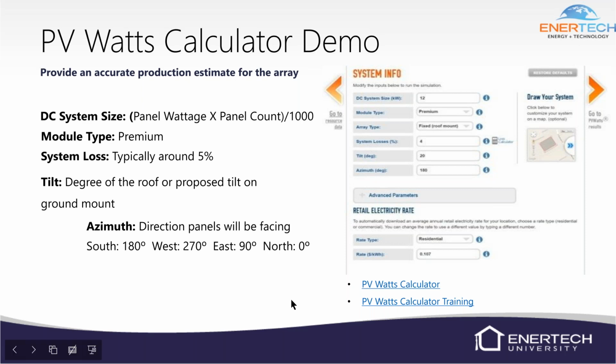So remember that the sun goes up higher in the sky in the summer and lower in the sky in the winter. So our tilt, our orientation to that, is we kind of play the middle. That's why we go for either 20 or 30 degrees, likely 30 degrees.